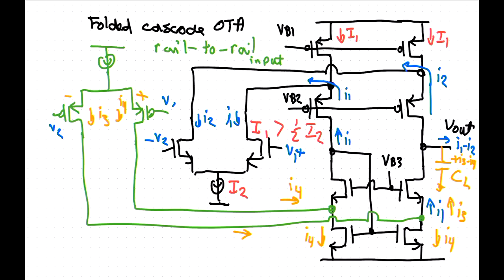Yeah, I'm struggling to understand the common mode. So the rail-to-rail input part. So how, for that I4 that's being injected into that NMOS cascode current mirror, why can we have that voltage be negative? No, you can't have it being negative. So what I've drawn here is a small signal current.